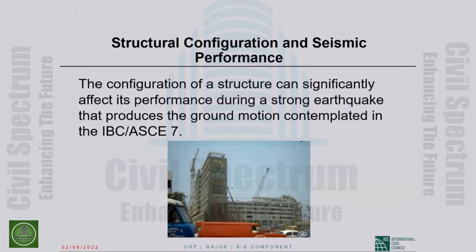Okay. And the picture shows the Ministry of Transportation and Telecommunication, Mexico City. I showed you the picture the other day. This was in the wrong height range. So it was kind of a resonant response, but the L shape of the building did not help. That meant a lot of torsion, which always hurts.